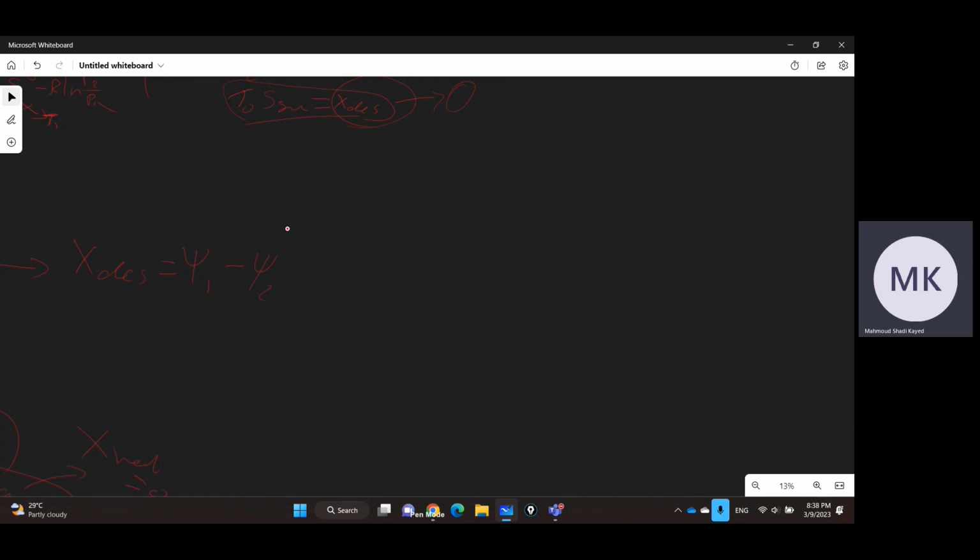So we combine these two in one formula, and we use for the open system: h1 minus h2 minus T naught times s1 minus s2, plus v1 squared minus v2 squared divided by 2. This will equal the Exergy destroyed. Now, as you remember, this h1 we find from the table of air at T1, and h2 we found from the energy balance. And T naught is given.